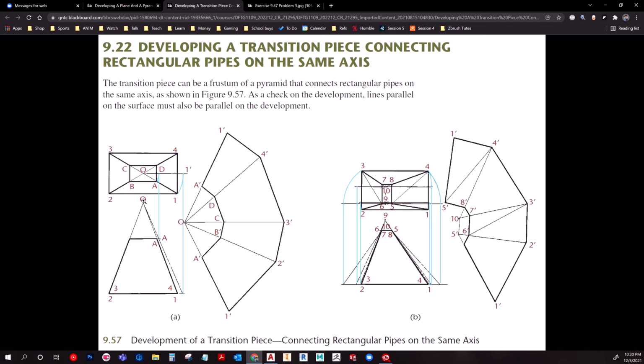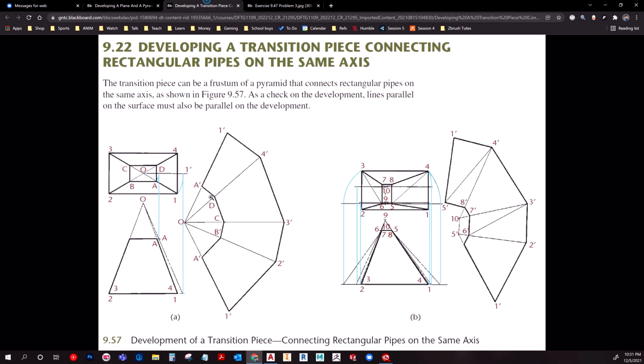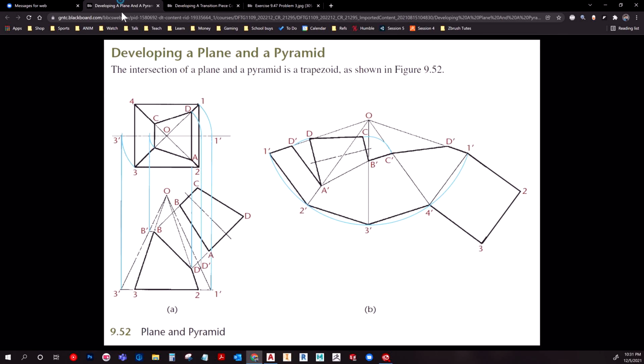So you would have a circle OA prime, and that's what you would see here, OA prime. The same thing applies to the outside. You would have O4 project down, and where that meets you would have O4 prime, which is the shape for all of these. That's cool, but what if you don't have a pyramid that is centered? Well, that's why I have this one here. The same concept applies to anything, not necessarily just a really crooked plane like this. It can be this, except off center.